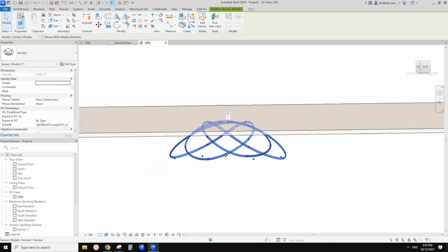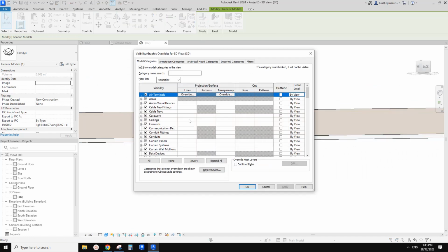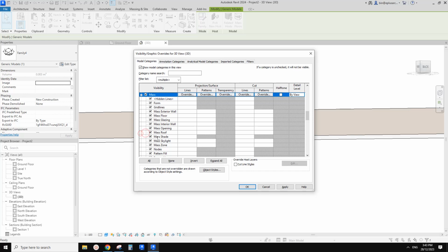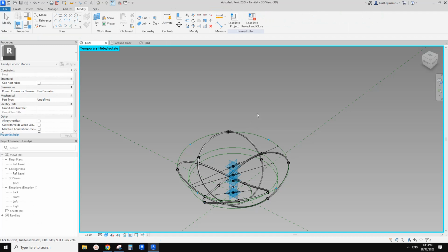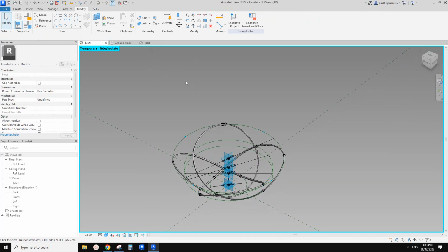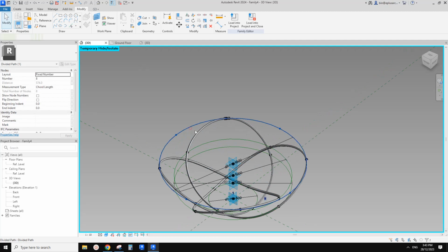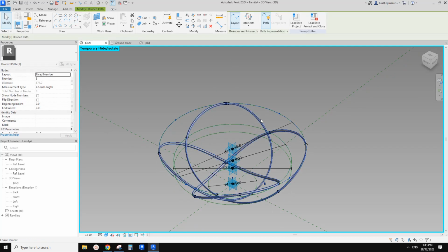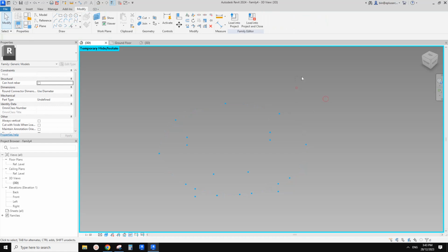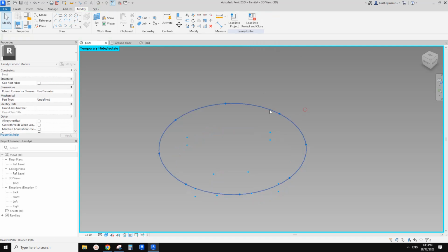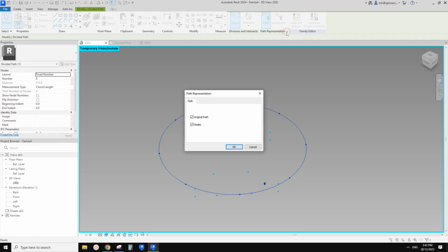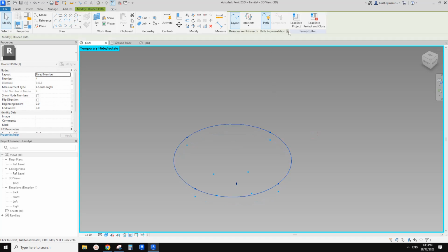And let's have those nodes. You can just go VV and turn off the nodes here, or you can just go to a family and then I think you need to select all these divided paths. So for example, I'll just type IC, and then select all these 4 and go to, looks like we can't do that. That's fine, just need to select individually and click on this little arrow, uncheck the nodes, so they will become invisible.